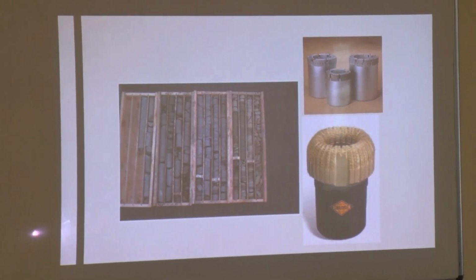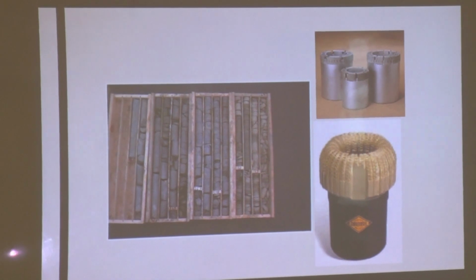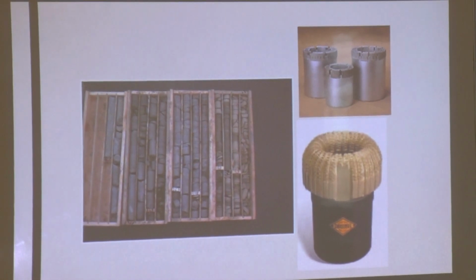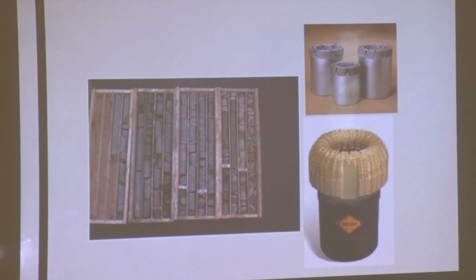But there might be one problem. Suppose you have drilled the core in such a way that it is perforated in between two joint sets. So no joint has been observed. So this is another limitation, a disadvantage of this kind of system.